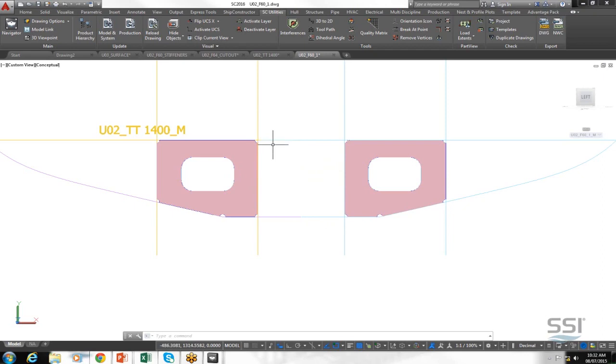So what I want to do is define this plate as a meter gap from my deck above. I want it to be a low plate. In order to do that, we're going to use an offset of my planar group plane construction line. Now I can see my planar group plane construction line doesn't quite extend to the bulkhead that I want to use, so we're going to again use AutoCAD's extend command to extend that outwards. So I think I missed it.